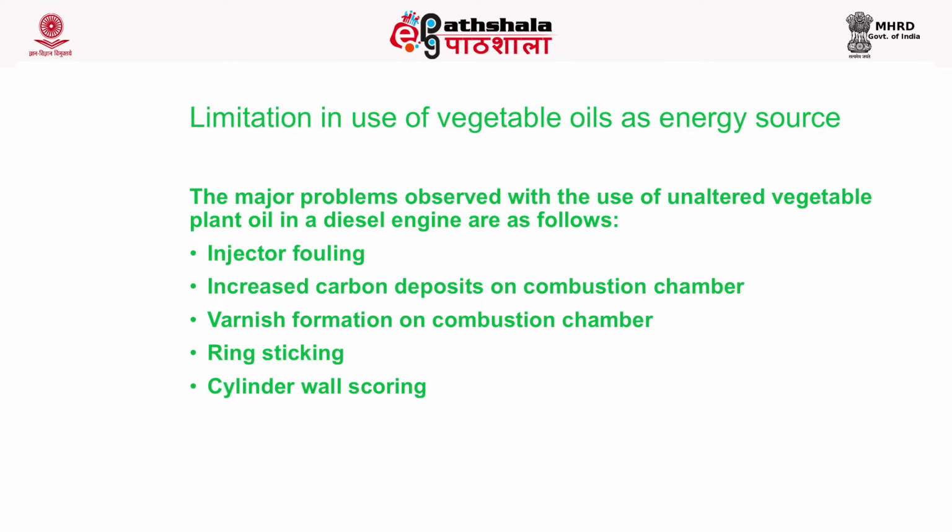Increased carbon deposit on combustion chamber, varnish formation on combustion chambers, ring sticking, cylinder wall scoring, and increased fouling of lubricating oil. So these are some of the limitations if we want to use the plant oil as such as the fuel in IC engines.